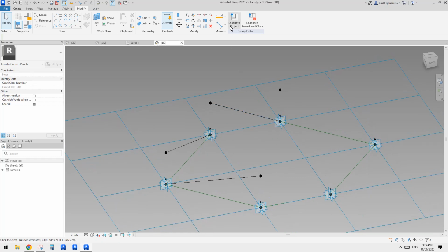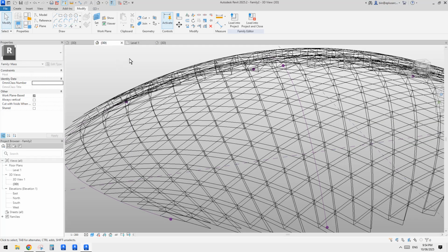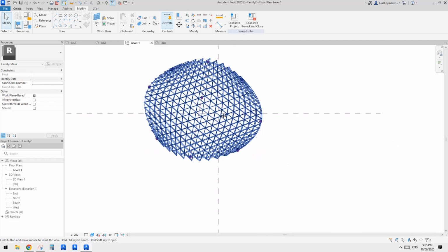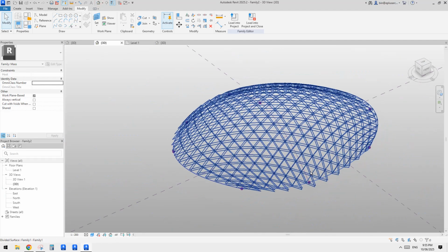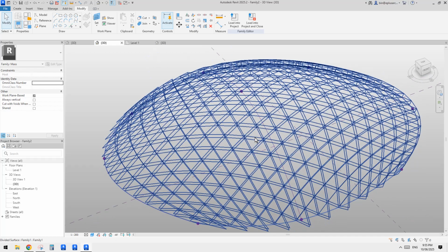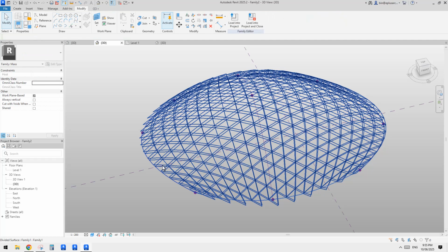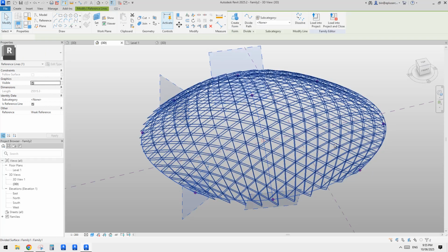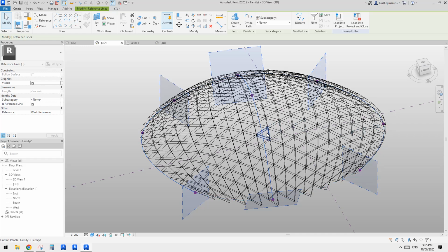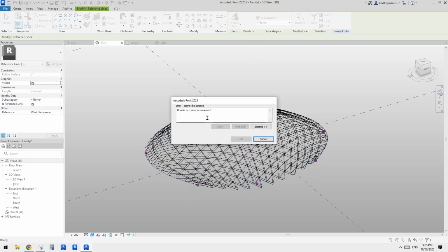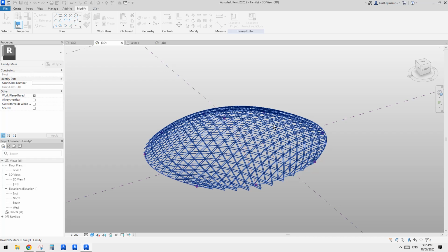Now let's load this one into the hang on, which one? Not this one, this one. So family 2. Okay, so let's load this one into family 2. And actually, so now we don't have a divided surface anymore, because we only create one. So let me try. Sometimes we can't create a shape from these 3 splines through points. Let's try. See? Okay, so don't worry.